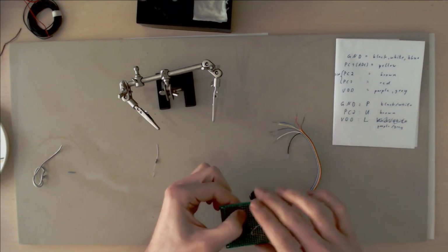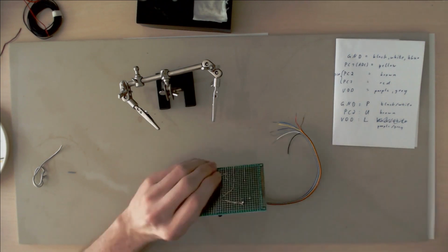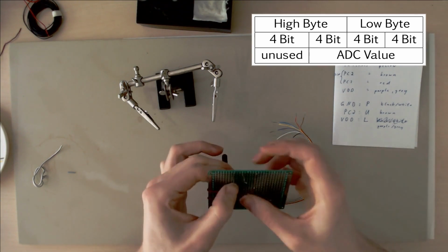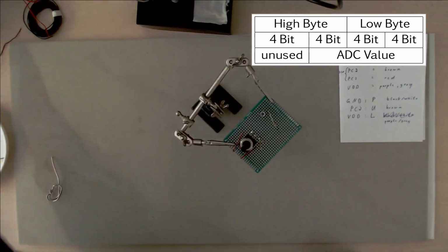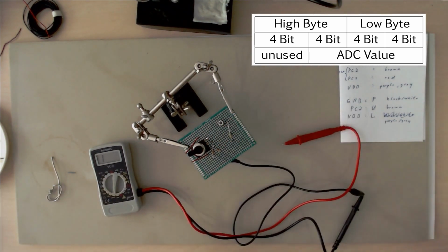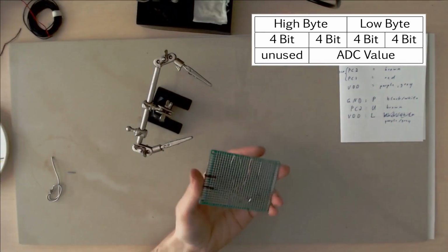The software on the controller is very simple. The AD converter is just read in an infinite loop, and after each conversion the digital input bit is set to an unused position of the 12-bit integer representing the analog value. Then the 2 bytes for this measurement are transmitted via a virtual COM port over the USB connection. That's not the most elegant way to do this, but by far the simplest one.